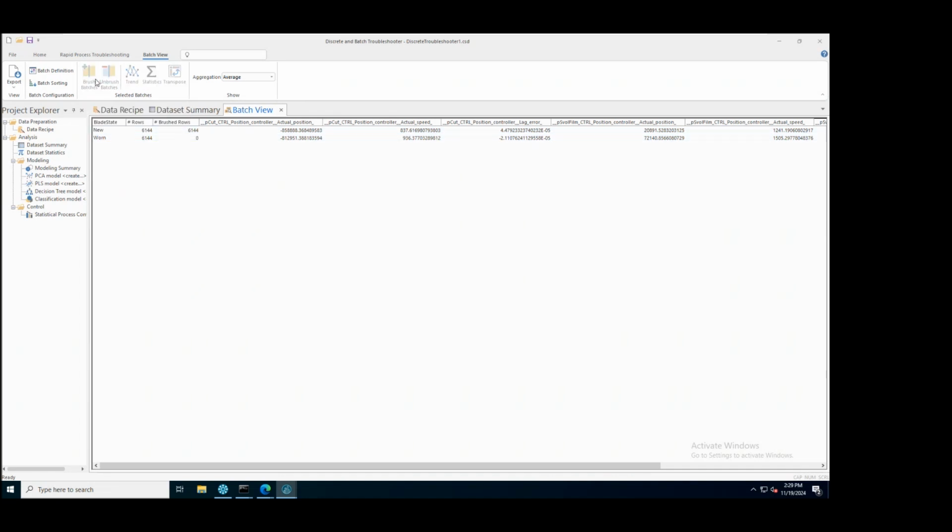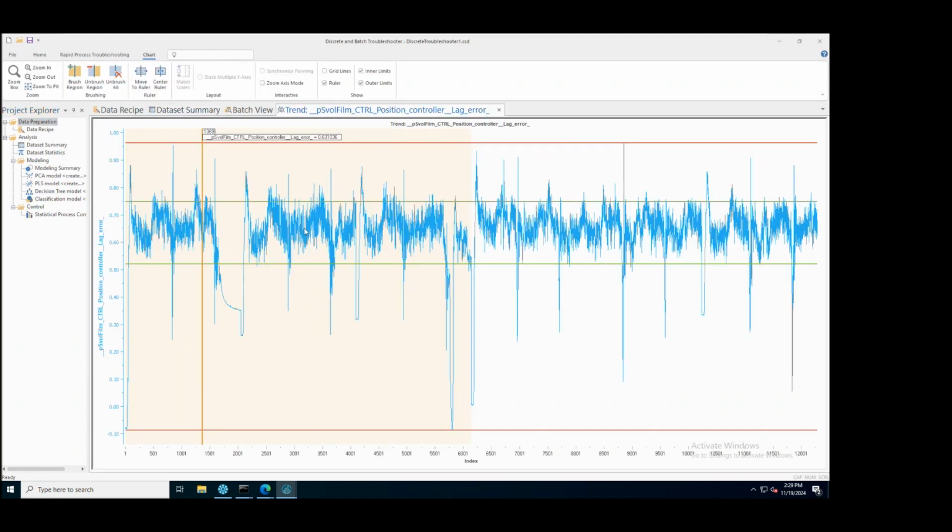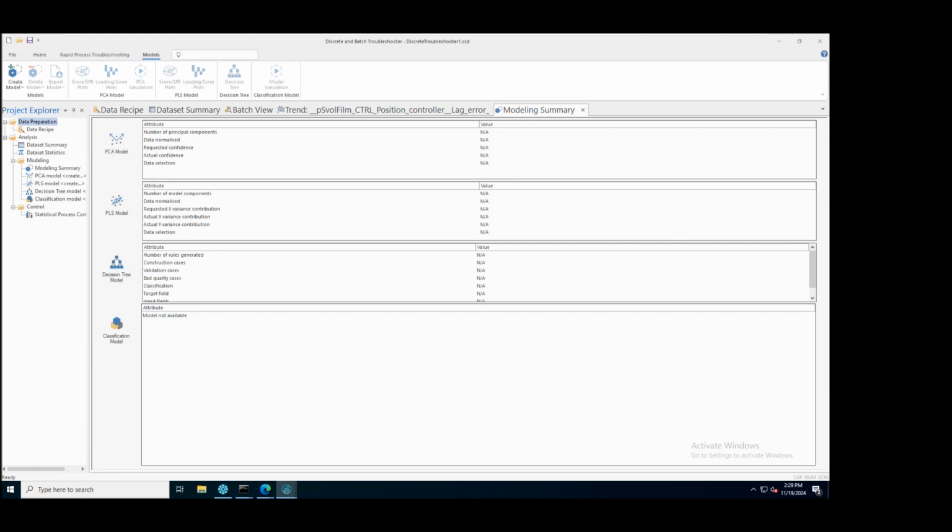We can highlight this information. We can say, I would like to brush all of these rows associated with the new blade. You'll see why this is especially convenient in a few moments, but this is also really nice from a visualization perspective. We can then move into the visualization and very visually see where the difference in the new and the old blade is. So once again, we can try and do this with our eye and determine what is the contributing factor between all of these tags, which will help us to determine whether a blade is new or old, and that can become especially difficult. In this case, we have some noisy data, which is not really that easy to interpret. So we will be using the principal component analysis model. All right. Principal component analysis is especially appropriate for this use case, and it is used very commonly in industry for this purpose, to try and determine whether a specific piece of equipment is degrading or behaving in an abnormal way from the way that it normally behaves.